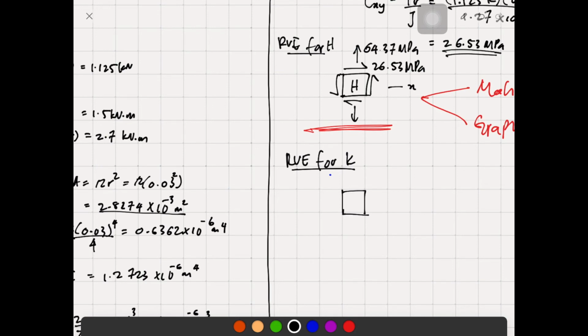This is again positive shear stress, with a magnitude of 30.06. This is the x direction, and on the y direction, now this is downward. We're going to have a negative value for this, and the value for sigma y, if you take point K, make sure you get this value.